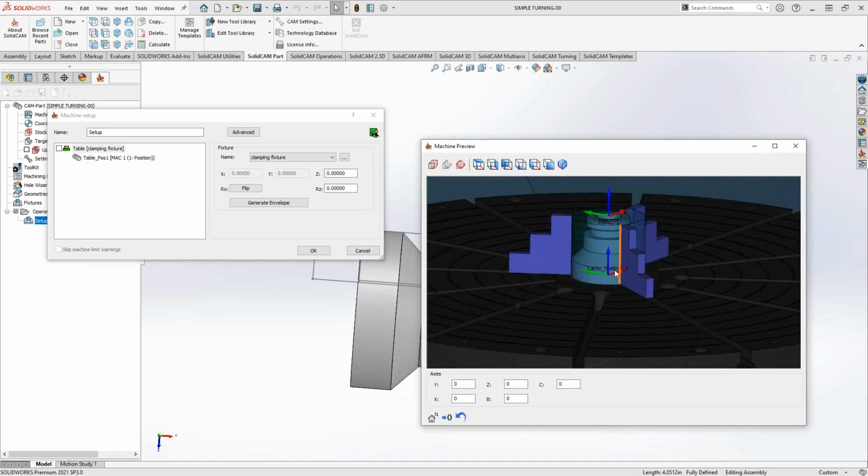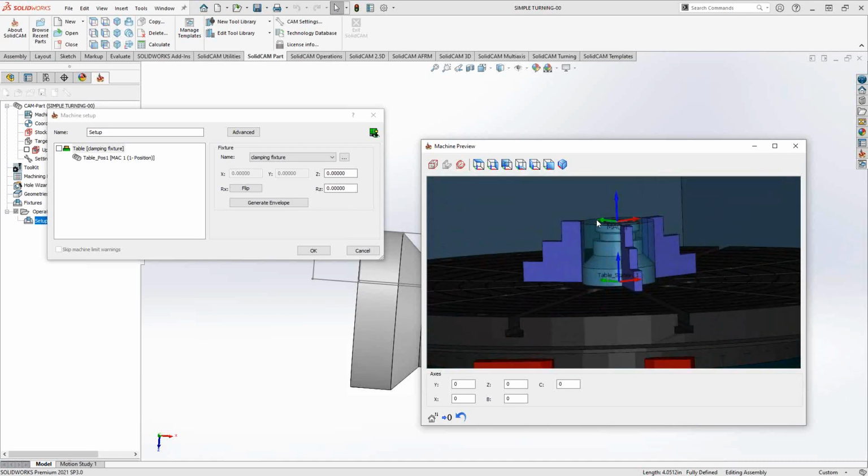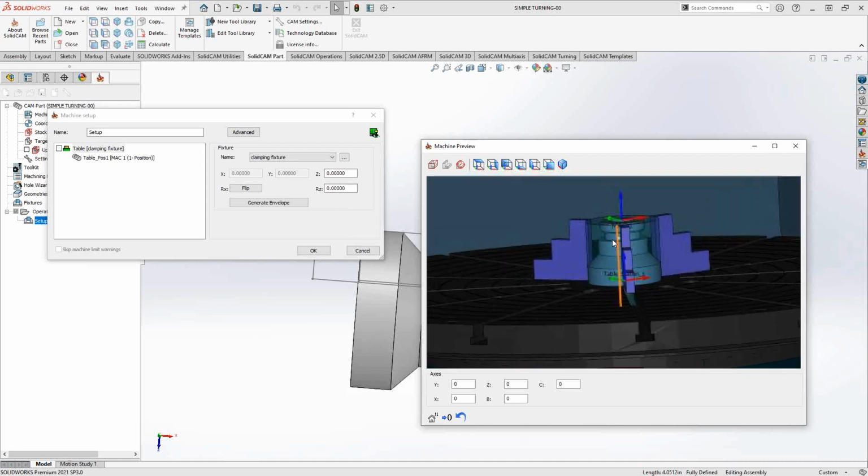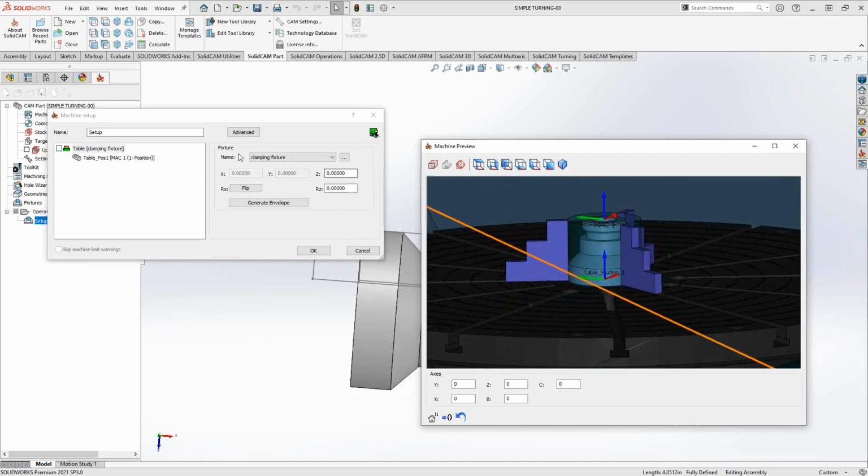You have your table face, table station, represented by that coordinate system. And then we have my Mach 1 position 1 that I defined there. The Mach 1 position 1 currently is aligned with that reference point of the jaws. Because that is there, it pulls out the stock and target to match that line there. The jaws themselves are defined as sitting right on the table. So that's why those guys are there and all that lines up like that. But in reality, I'm probably not holding onto my part right on size there. So that's what all these Z values are for.